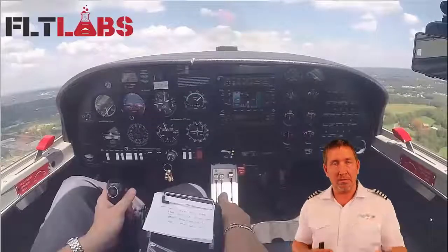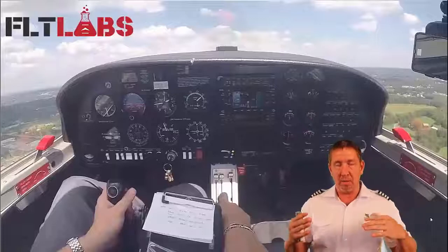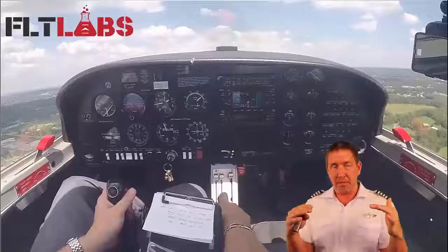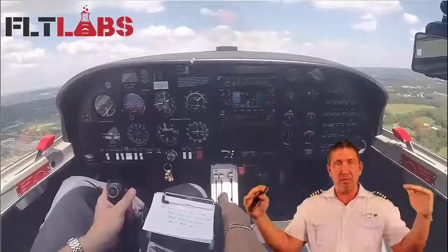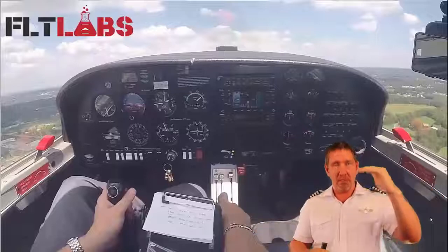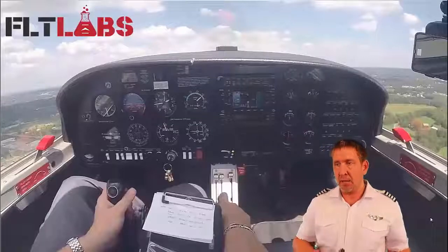Okay, great, welcome back. So not a big deal, it was a pretty smooth transition when I went from the flaps and the takeoff to the flaps up. I really focus on maintaining a good pitch attitude with my horizon, meaning the difference between the cowling and the horizon and so forth. So now let's finish up.